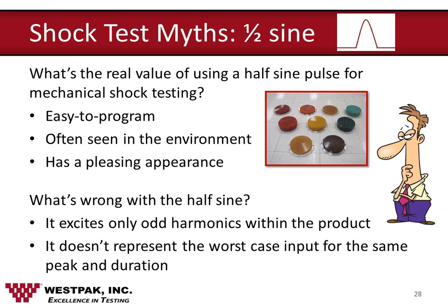I don't know. Other myths are important too. Given that we've previously shown this half sine shock pulse myth, one could easily question why the half sine pulse is used at all in the process of fragility assessment, reliability testing, or anything else. Remember that its response spectrum was less intense than that of the trapezoidal pulse. It turns out that the half sine pulse is very easy to program on shock test equipment.